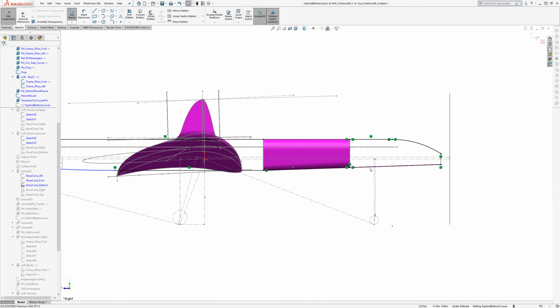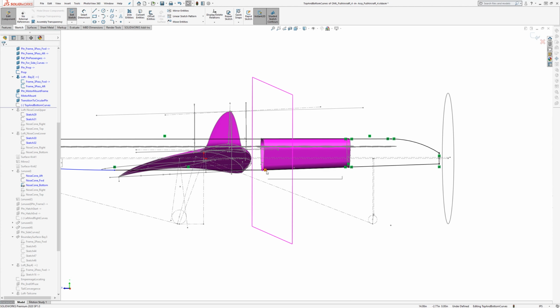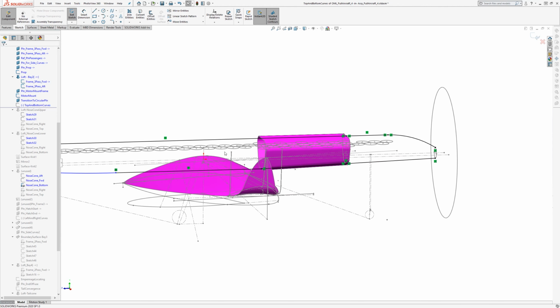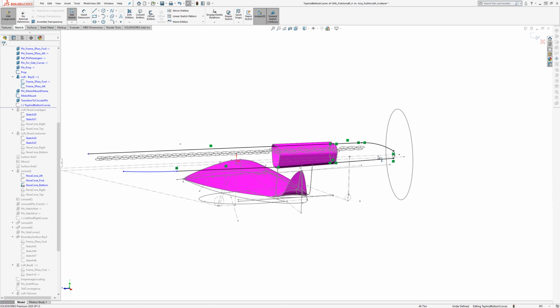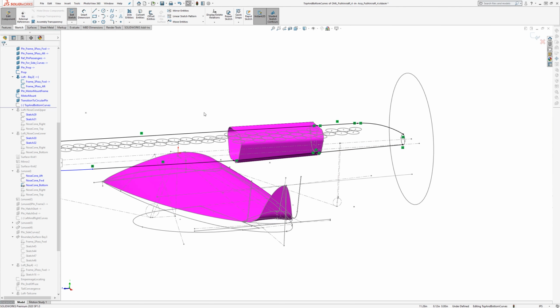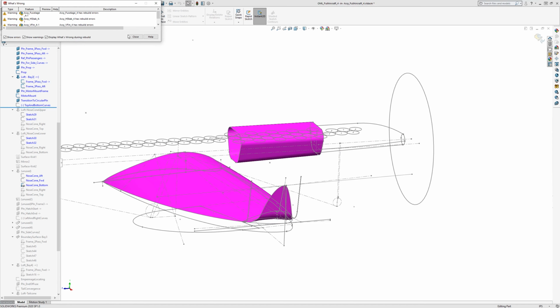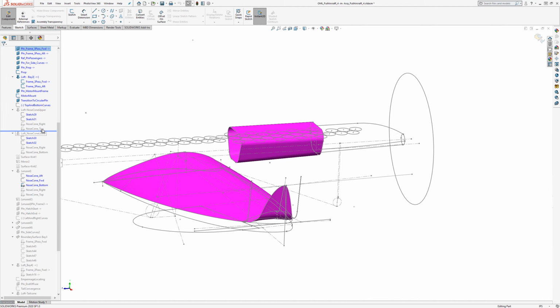So generally you don't want things to change curvature too quickly. For instance, you can make sure they're collinear. One of these frames might be driving the angle that this comes down at, but then we want to make sure that it continues at the same angle, so that ends up collinear, and then the point gets used to create that frame. So the design intent was just to keep things smooth, and it's up to you to work out what drives what. I liked working from the front backwards.